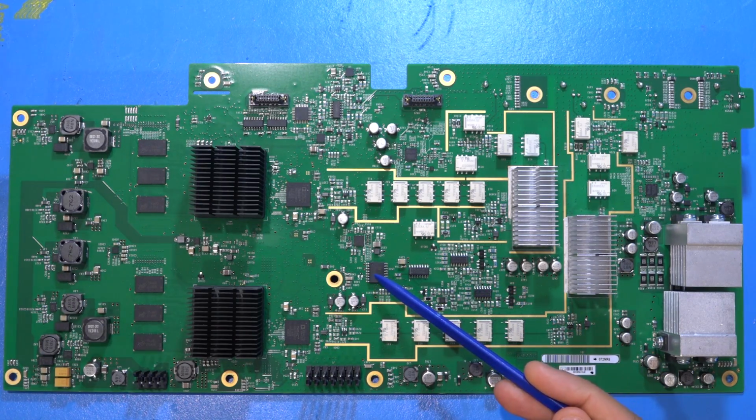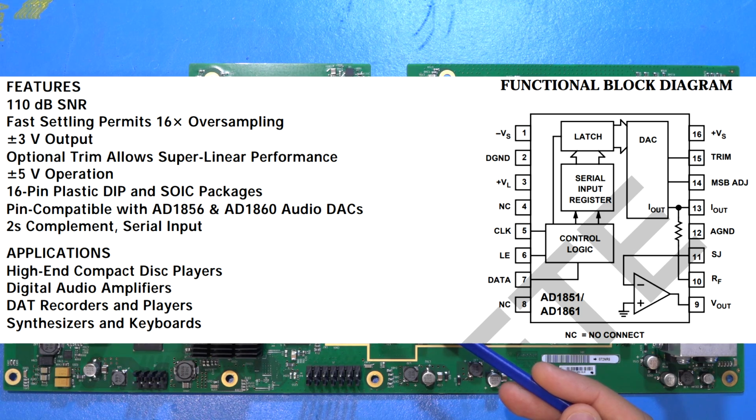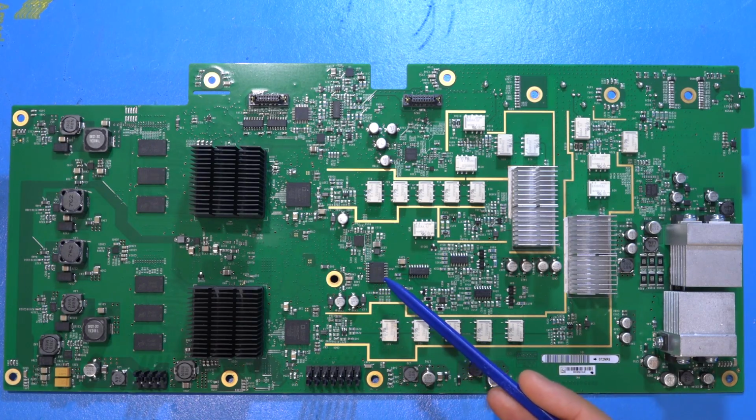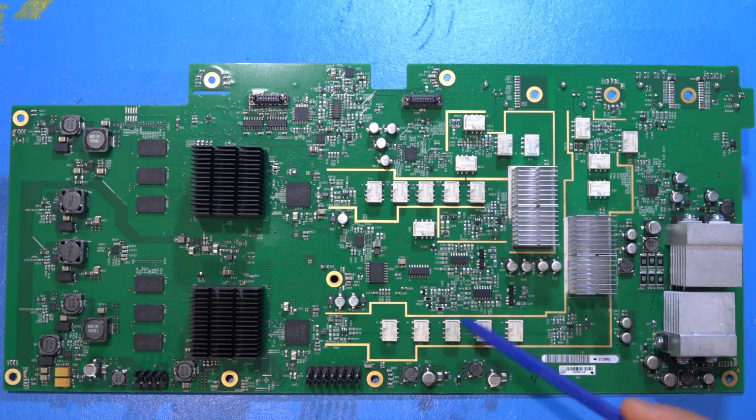This is an 18-bit DAC, a high precision audio DAC, most likely used to generate some precision DC offsets, signals to be applied, or maybe even some low frequency signals, but it is obvious that it's common to both channels. After that, we have an analog mux. This is an 8-channel analog mux and some op amps.